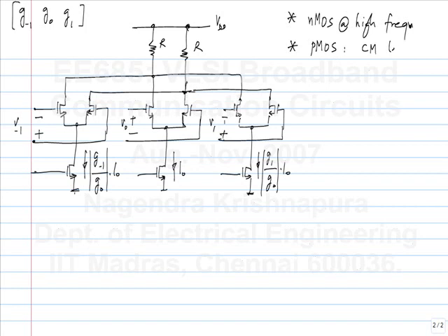With Pmos, the common mode level is closer to ground. This is usually not a big issue, but if it is, then that could be one reason to use Pmos. I don't know, it depends on what the receiver is. If the receiver is such that it needs a low common mode voltage, perhaps it's an issue. So, I mean, this is if it is constrained by the receiver.